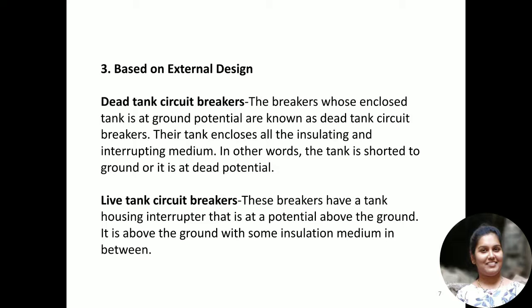These circuit breakers whose enclosed tank is at ground potential are known as dead tank circuit breakers. That is, the tank is at ground potential. The tank encloses all the insulating and interrupting medium. In other words, we can say that the tank is shorted to ground or is at dead potential. Either grounded, or it is at zero or dead potential. Okay, this is the dead tank circuit breaker.